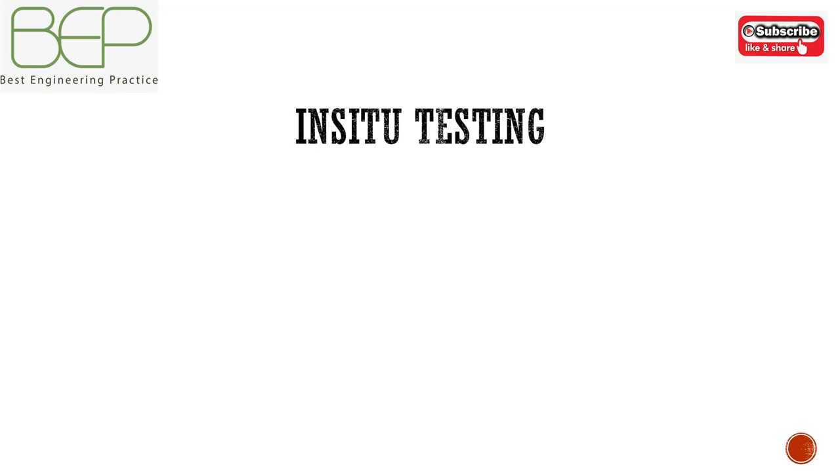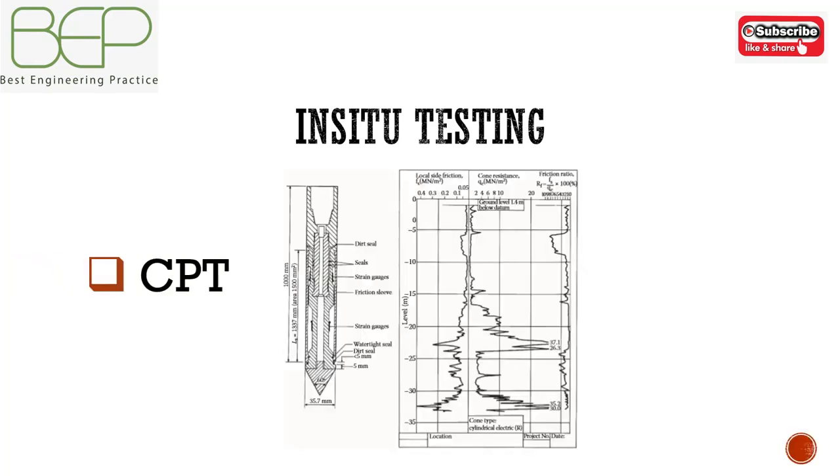In softer and looser soils, the use of the CPT is preferable. A 60-degree cone with a 10 cm² face area is pushed into the ground at the rate of 2 cm per second. The force necessary to advance the cone is measured. A 150 cm² friction sleeve is typically fitted behind the cone and measures shear stress between the soil and the cone at this location.